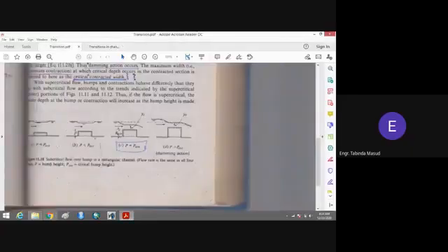You can see here that this is a mild slope, and here we have a hump. The height of the hump is P. So what will happen? Water flowing in the channel, when it approaches the weir, there will be a small depression in the flow, and again it will come back to its original state.